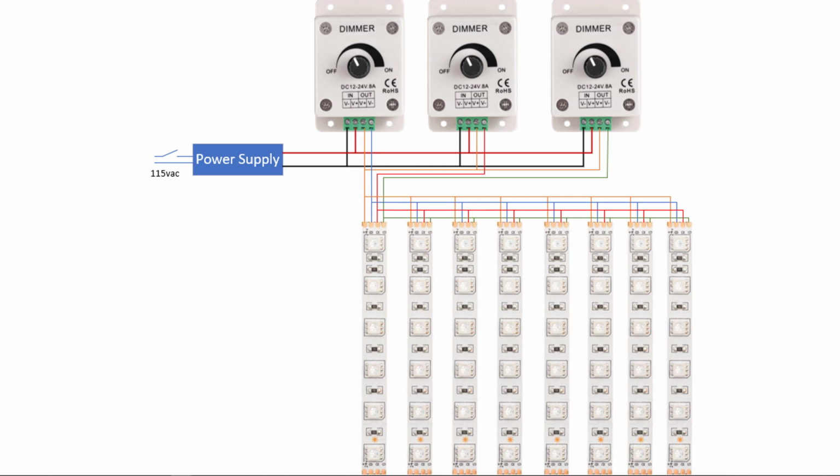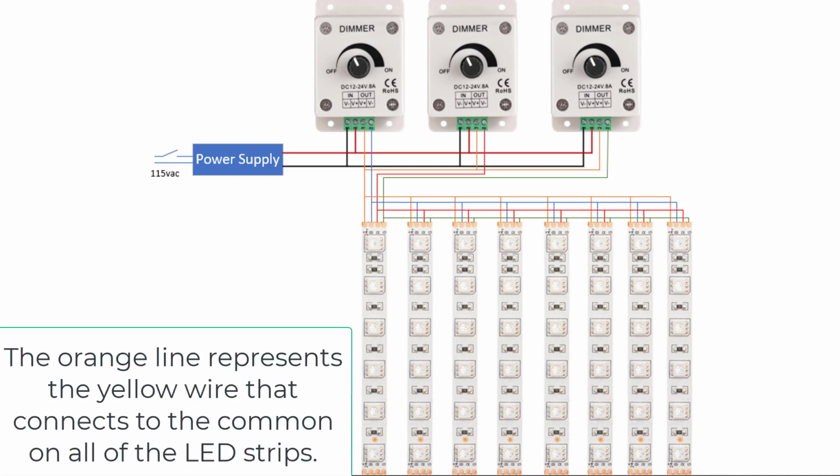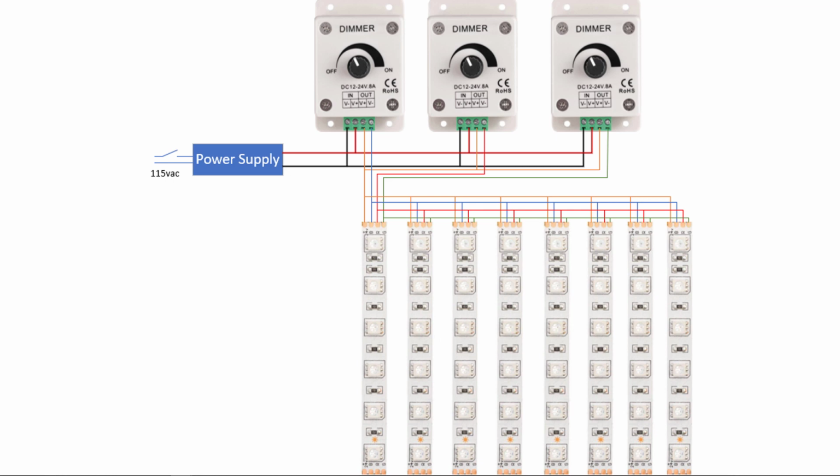And coming out, the orange wire is the plus out. So that feeds the plus voltage out to all 3 colors. And then the amount of current allowed through each color is regulated or controlled by the circuitry in that dimmer, from the blue, the green, and the red wires coming back from that LED strip.